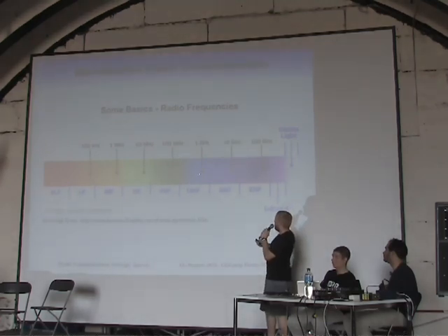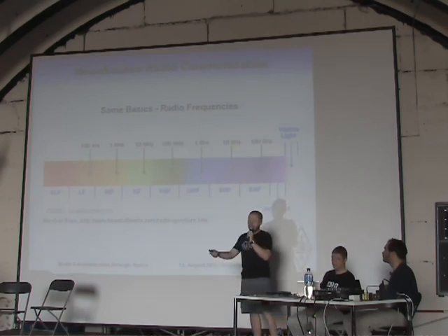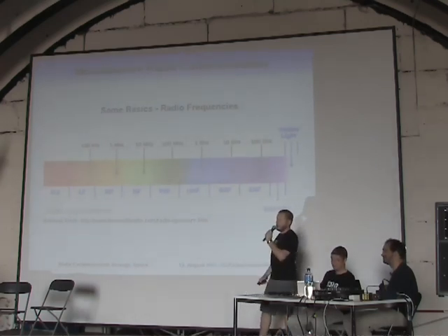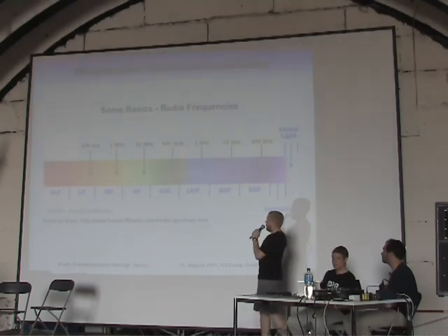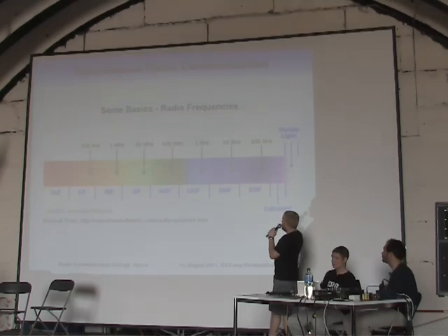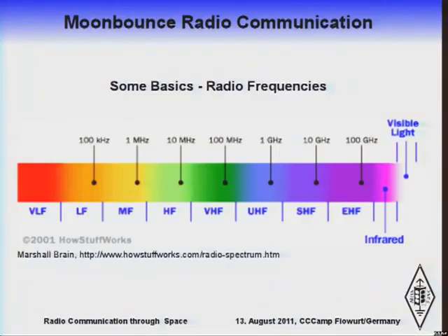Quite a bit farther up, below 1 gigahertz and above 1 gigahertz, you have GSM radio, which you just heard. So signals travel line of sight. You don't have any wide ranging communications there except with high power, and if there's no obstacle in between, which would mean through space. So you can do that. Communication satellites are in this area, 10 gigahertz. It's very good to reach space through the atmosphere, which doesn't disturb it too much except when it's raining.